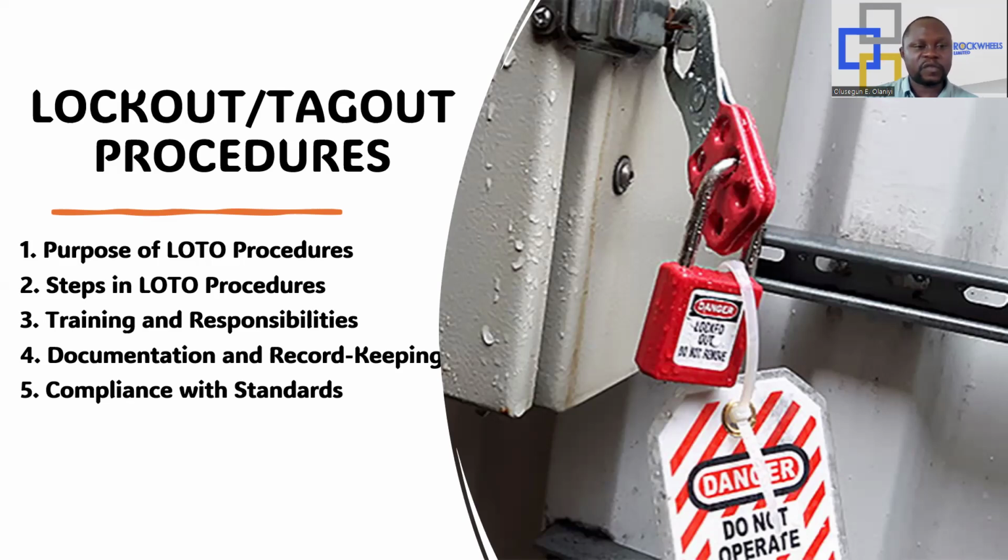So remember I said we have procedures for LOTO. The first thing is to prepare. After preparation, you shut down the equipment and the machineries using the normal operating controls. And you ensure all stored energy, such as the capacitors or the springs, is safely released so that there won't be energy on the line. Having done that, you do what we call isolation. By doing isolation, you are disconnecting or isolating the equipment or the machinery from its source of energy. Then you use log out devices, e.g. your locks, your chain, or your valves, to secure the isolation point.